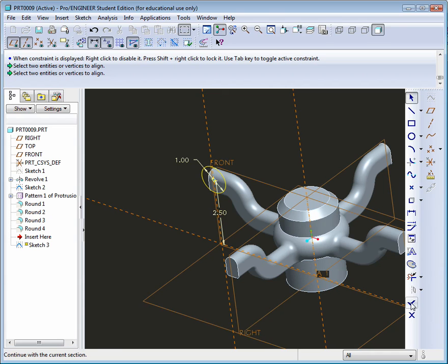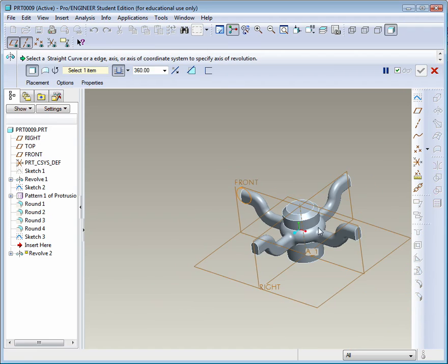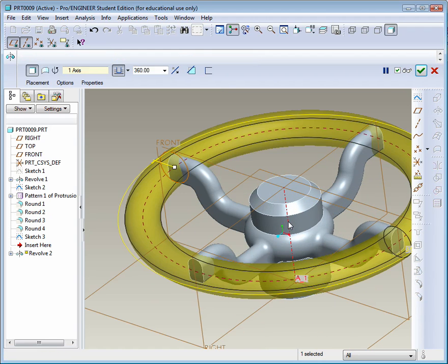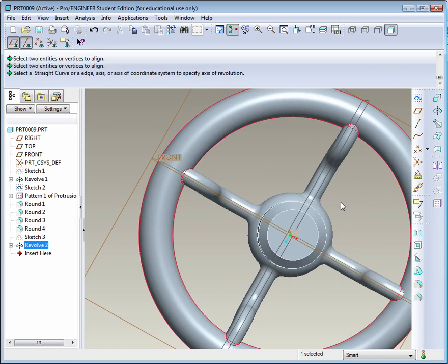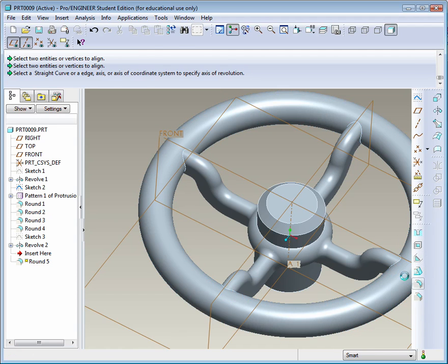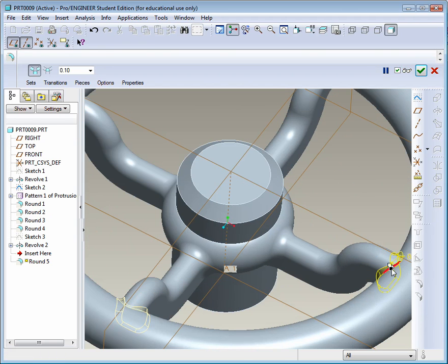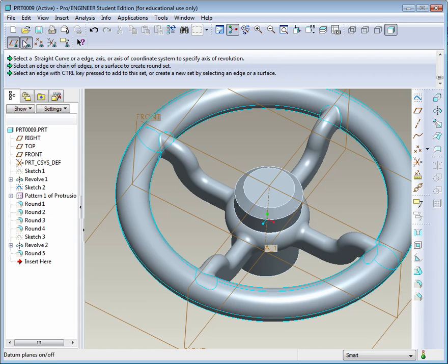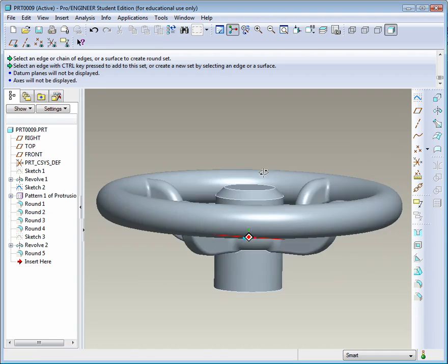So we hit the check mark at the bottom right, find the revolve feature, and we could select the axis in the center and apply it. Finally, let's finish off with some fillets. Go to the fillet tool and select these edges to add your rounds or fillet. You can turn off your plane and your axes if you want to see this without obstructions.